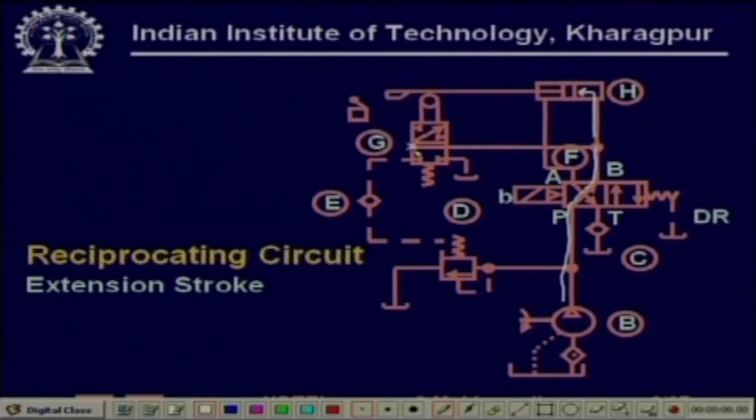So, this side is off. This side is off means the relief valve port is plugged. Therefore, the full pressure is actually applied to the load. The pilot port is plugged, and this cylinder is moving this way, right. So, this is the extension stroke.